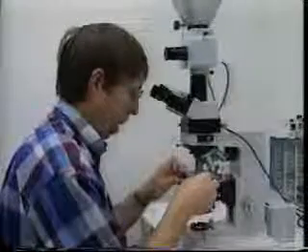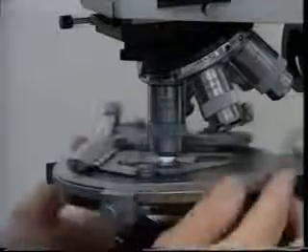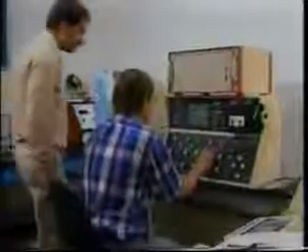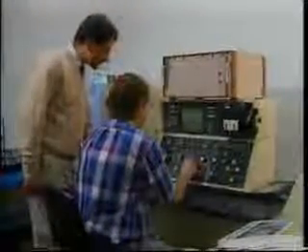The selection of acid and additives depends on formation composition. Lab tests are valuable in such determinations. Thin section studies of reservoir rock are effective in identifying clay material and rock composition. The scanning electron microscope is capable of revealing much greater detail. It can be used to find minerals that can potentially damage the reservoir flow channels. Once found, precautions can be considered and remedies incorporated in the treatment design.